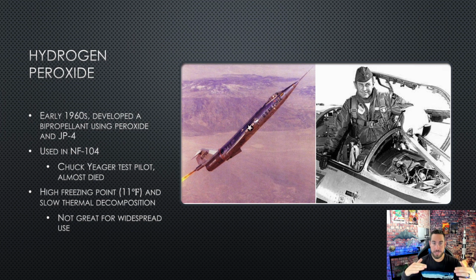How airplanes fly relies on those molecules flowing over the wings to maintain lift. So you get higher flow above the wing, which means you have higher pressure below the wing, which keeps it pushing up. When you get into the high atmosphere, you don't have as many molecules flowing over, so you lose dynamic control like that. You can't use your typical control surfaces. So no one really knew what the performance envelope was going to look like with this F-104.